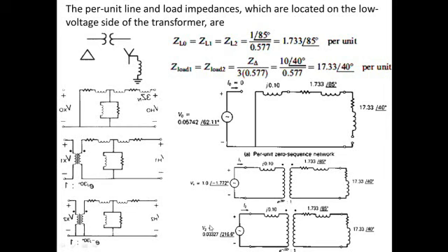This voltage we already derived, we just convert this value into the per unit value, the per unit equivalent reactance, the transformer delta to Y conversion, the phase shift 30° plus in case of the positive and 30° minus in case of the negative sequence. And similarly the line impedance and the load impedance.